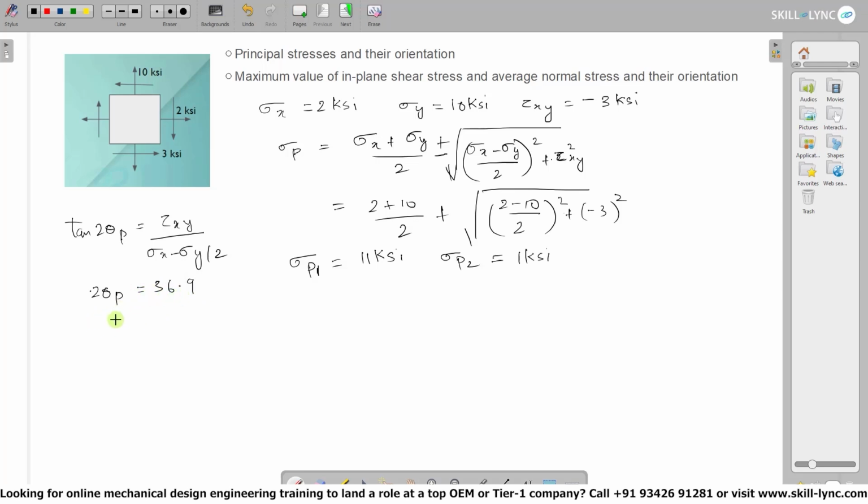So we came over a few observations which were given for principal stress or for plane normal stress. The 2 theta value ranges inside plus or minus 180. So basically 2 theta p1 to 2 theta p2 falls under plus or minus 180.